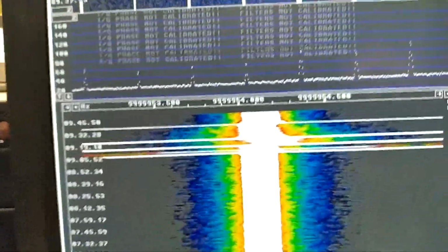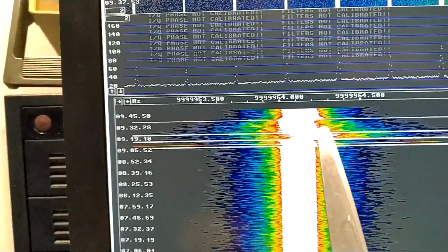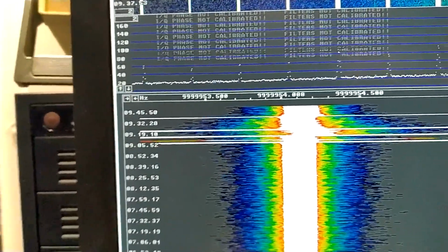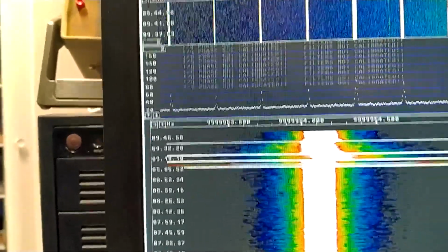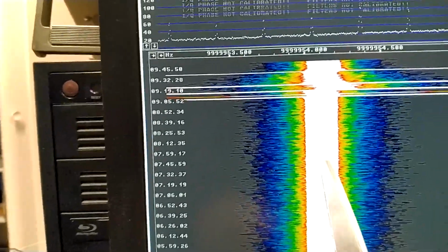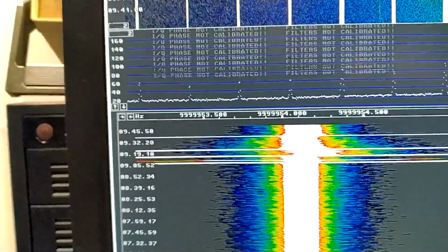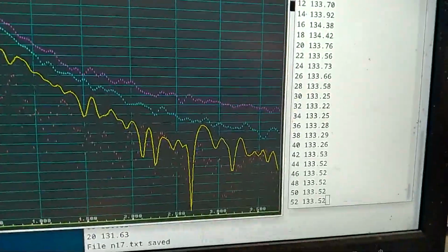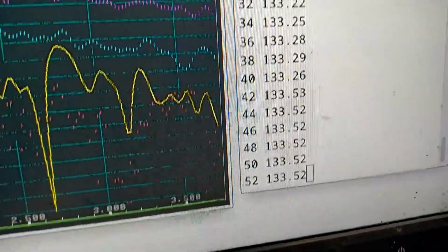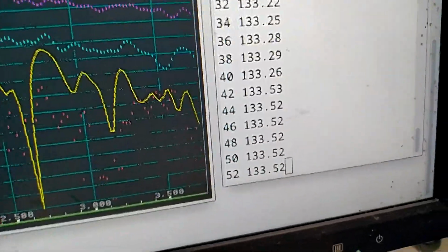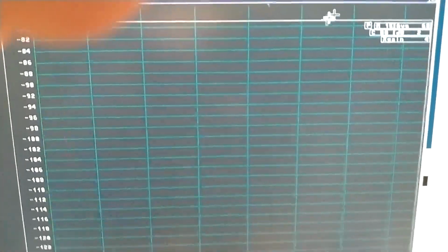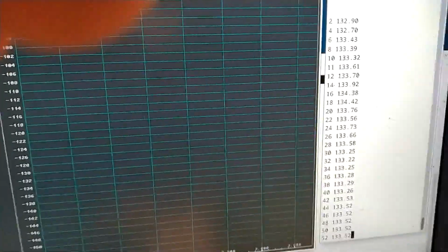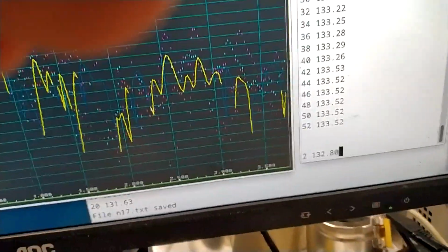Frequency drift is getting significantly slower here, and the noise is becoming much lower also, similar to what I had here when running overnight. And the average is now minus 133.5, and I reset the average collection again, here. So I start collecting again.